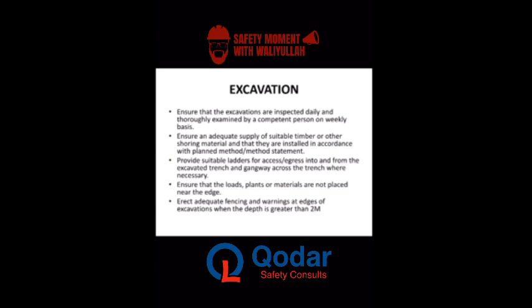Excavation is also another advanced form of digging. When embarking on an excavation task, we want to ensure that the excavation has been inspected by a competent person. That is, having conducted all plans, seen the EIA of the existing place that needs to be excavated, and verified that there is no existing facility there. We want to ensure that adequate shoring material is provided.